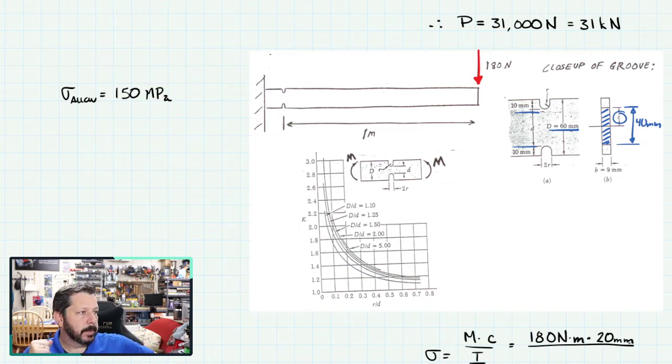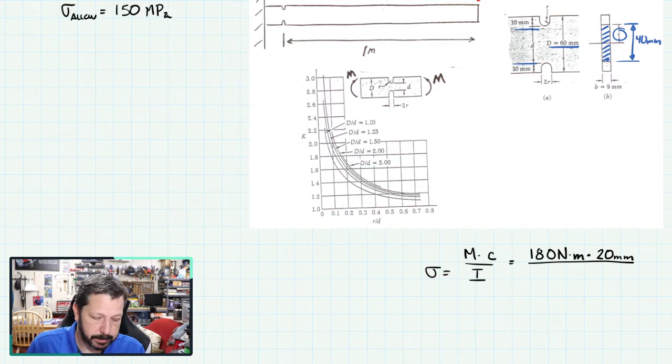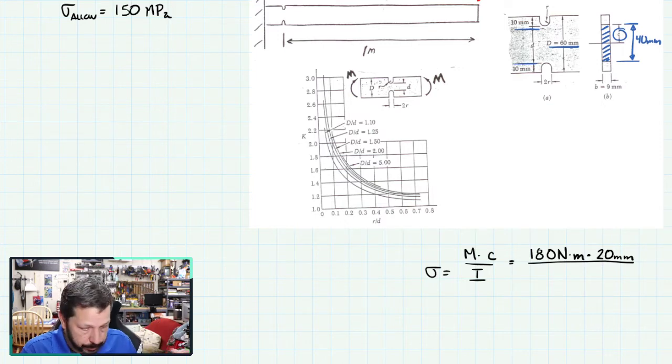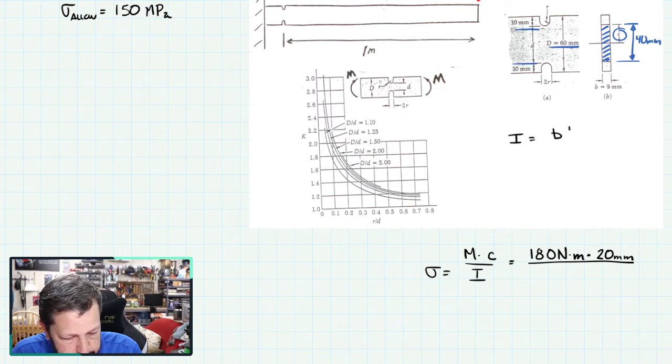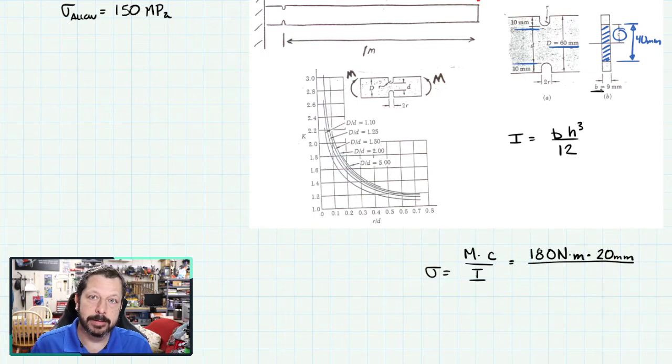And then a little bit off the bottom there. There we go. I, this is a rectangle. The rectangle that I shaded in blue is what I want the moment of inertia of. If you don't remember the moment of inertia of a rectangle, you have to go to one of your reference charts to look that up. I do happen to remember it's I for a rectangle is BH cubed over 12, where B is actually labeled B. Sometimes the label letters don't match up with what the variables are, but in this one they actually match up.